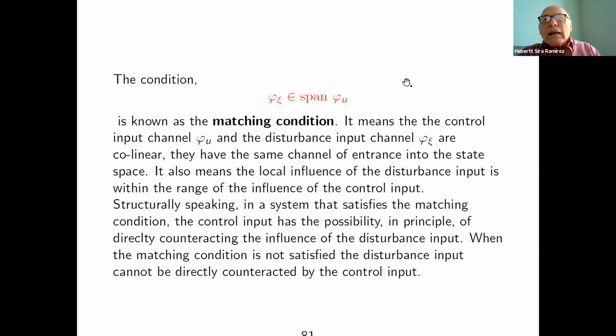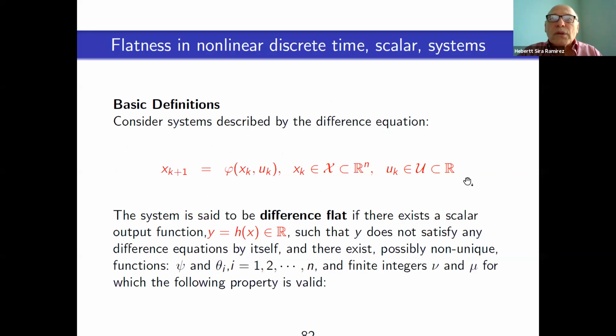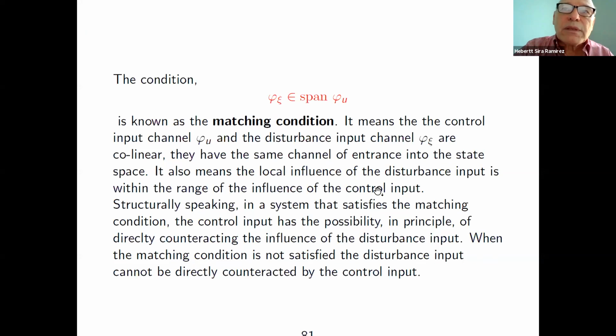And therefore, there is something that you should be able to do. Alternatively, you can think of a transfer function that attenuates that input, so that if you have some frequency information about those disturbances, then you might include in your feedback control something that attenuates the effect of those disturbances appearing in your input equation. If the matching condition is not satisfied and you don't have any control acting currently in the system, then of course the disturbance will be uncompensated.